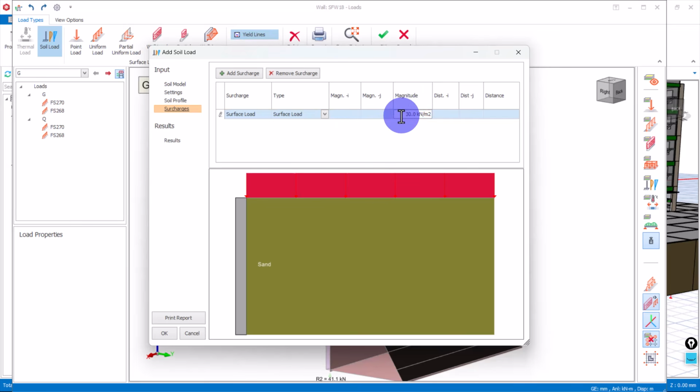Then coming here now, this says magnitude. What is the force? What is the load on this? So in this case, since the top of the basement is for just normal cars that will be using it for day-to-day activity, coming in, dropping off people for the hotel, and based on the Eurocode standard, load for cars, when I mean cars, I mean saloon cars and SUVs, not all those heavy duties like bulldozers, load for cars ranges from 10 kilopascal to 20 kilopascal.